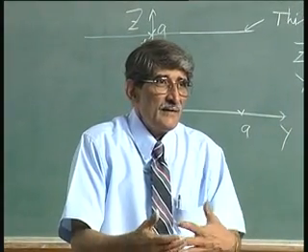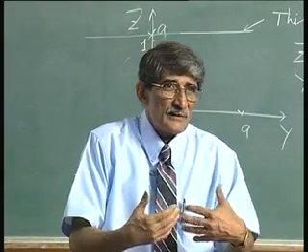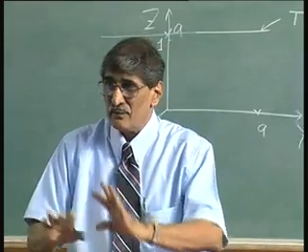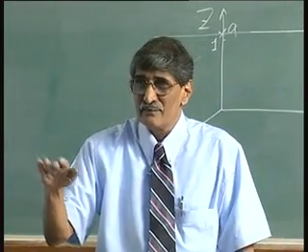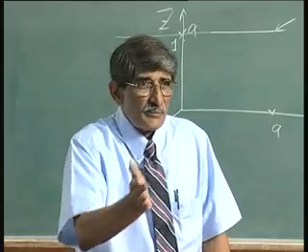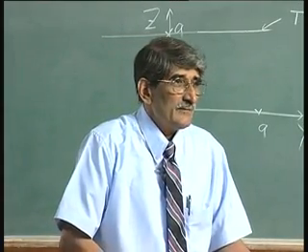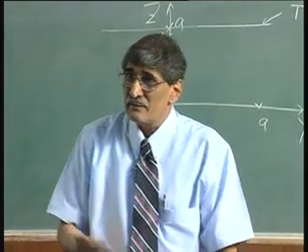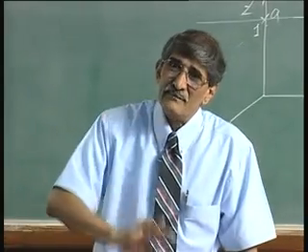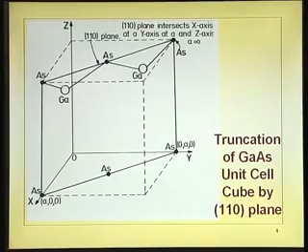I am calling it 1 0 0; we are not really distinguishing between 0 1 0 and all that. If you cut any one of those planes, the property will be the same, because the arrangement of atoms is the same there. That is why you call it the family of 1 0 0. Similarly, you call it 1 1 0.